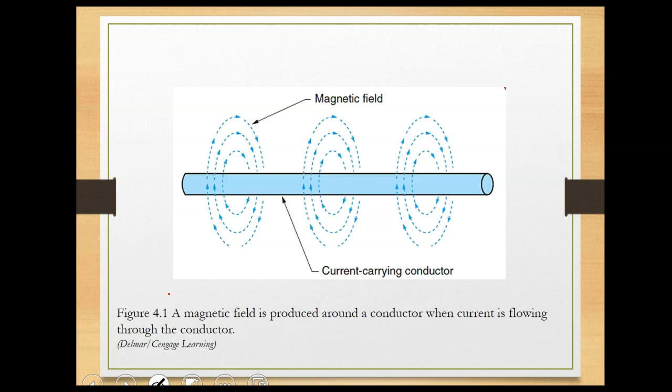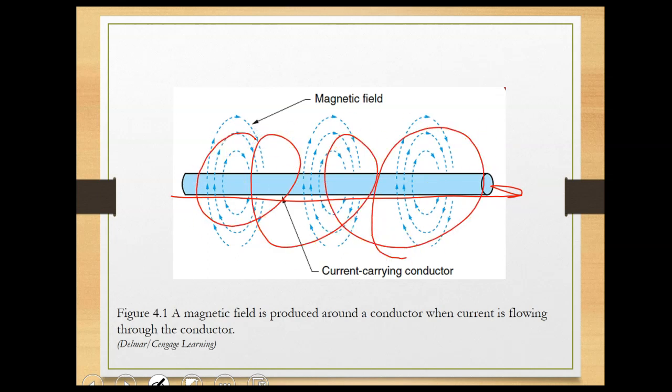So this is kind of explaining how we measure the magnetic field around a wire. Whenever we have current running through the wire, there's a field going around it, and that field is measurable depending on how strong it is. This is the basis of using the voltmeter pen, which lights up whenever it detects voltage, and also the clamp-on meter that measures the field around the wire.